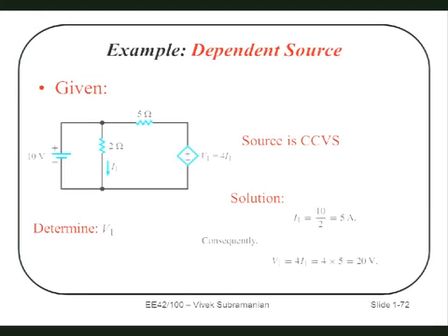I said 10 volts, but I had automatically chosen a ground. What was the ground that I picked? I picked this as my 0 point because 10 volts is really only between the 2 points on the battery. So you see how we internalized that. We automatically picked it, then we calculated current, and then figured everything else out. When we provided this voltage, again, we referenced it relative to this point, which we call ground. It's the negative of both of these sources, so it's convenient to call it ground. That's why we did it that way. So we're done with this section.